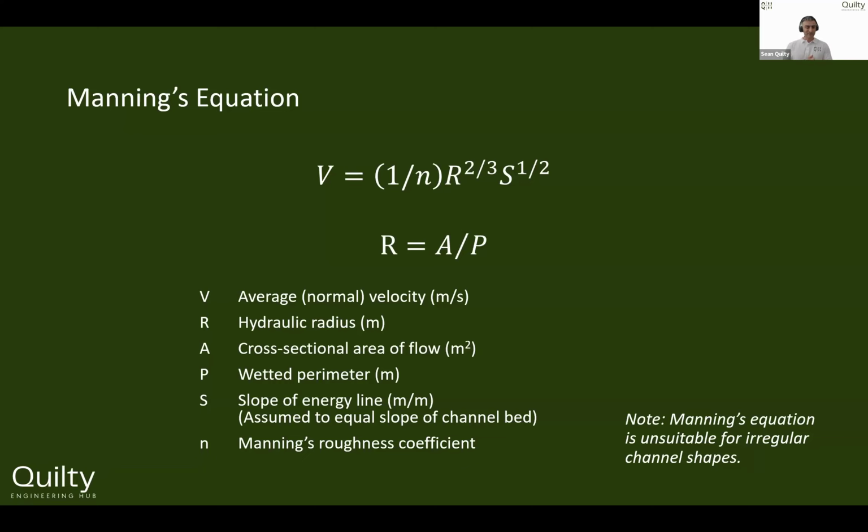The slope, please keep in mind that's a decimal, meters per meters. Don't use percentage. Sometimes, depending on the values, you can get away with it and get an answer that seems correct. And then other times it'll throw it right out. So just keep an eye on those units.